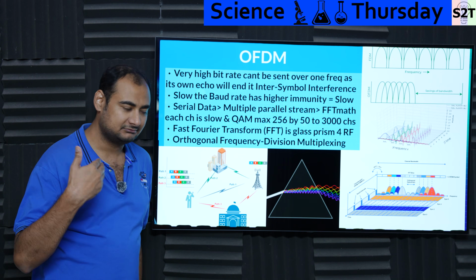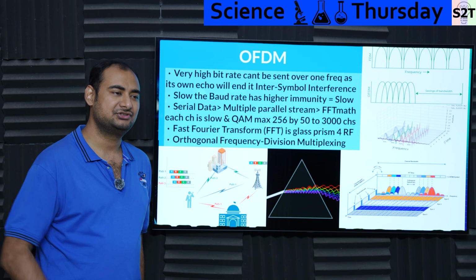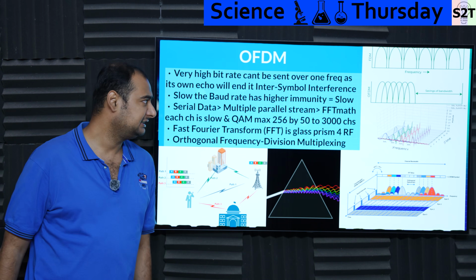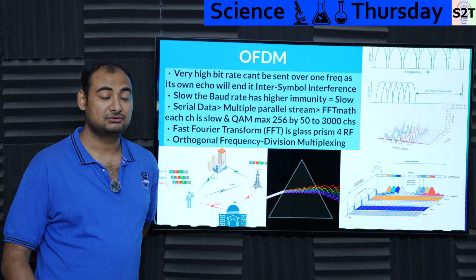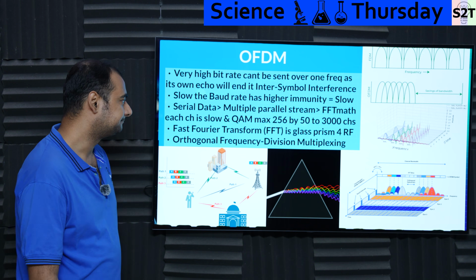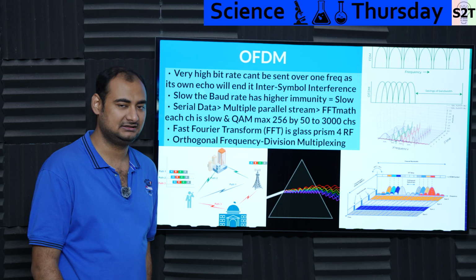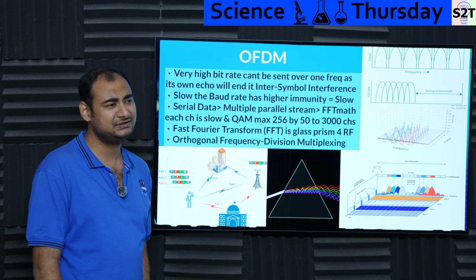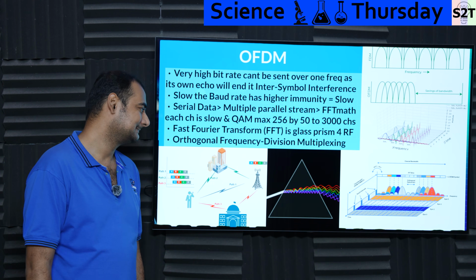This is the reality of everything. Any signal that you think about is generally this OFDM carrying QAM. Now generally QAMs, when you're talking about a mobile phone, are generally 256. Not bits, as in 256 map, that coordinate map would be 256. Because again, you can go very high, it just will not be legible. Mobiles have to work over very long range, so they are only 256. And even 256, generally they downclock to 128.